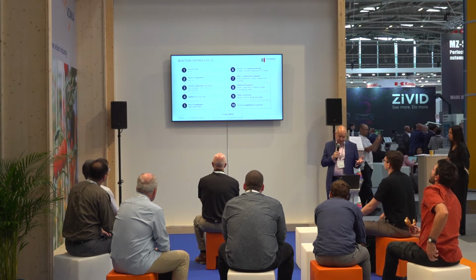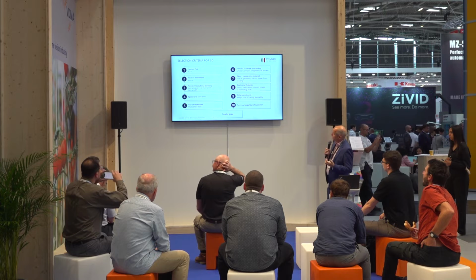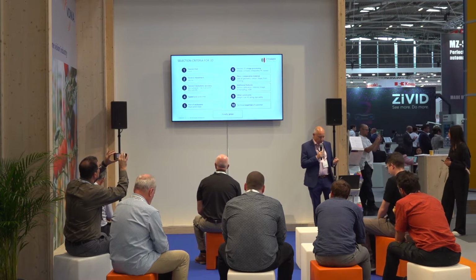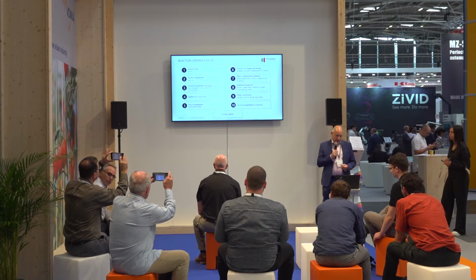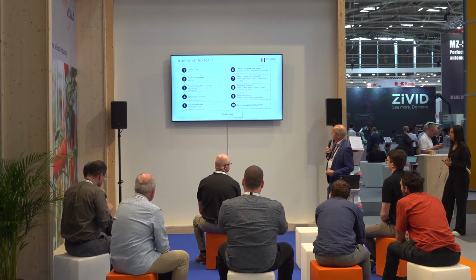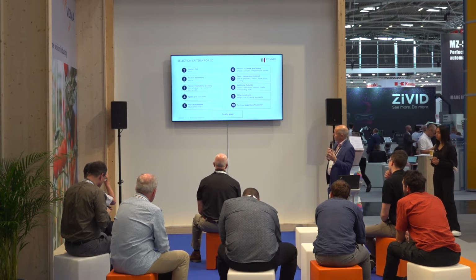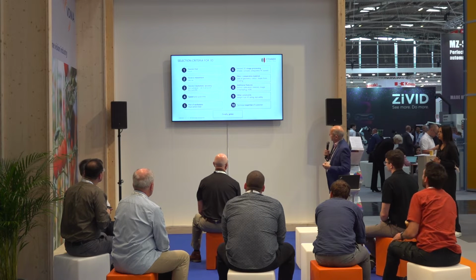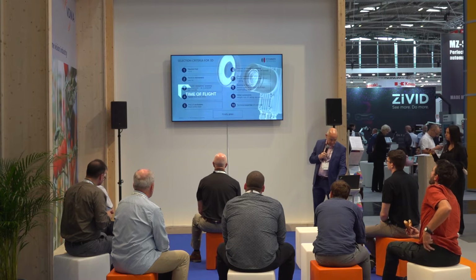Of course, we need to have a specification of what we're looking for, to identify what we want. So one of the first things is let's ask the questions. What's the field of view? What's the relative movement? How large an area do I need to look at? Is the product moving? Can it be held stationary for a period of time? And how do you want to integrate this data into your wider system? And also, what's your expertise? Do you want to build everything from components, or do you want to have a ready calibrated system? And the environment, things like that. Lots of things need to be taken into consideration when choosing the right product.